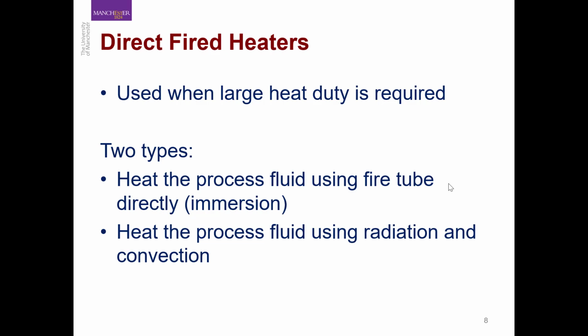As you can imagine, when we were talking about indirect fire heaters, we had an intermediate fluid transferring heat from the fire tube to the process fluid. And if you remember from heat transfer, the more mediums are involved in your heat transfer process, the more resistances you have. So the intermediate fluid was causing an additional resistance to the heat transfer.